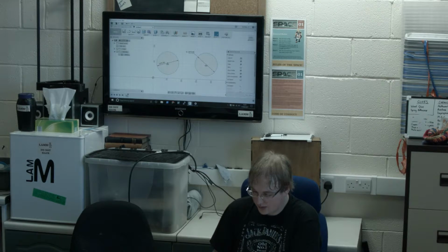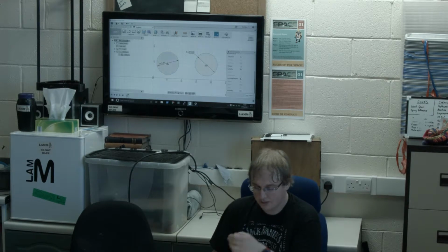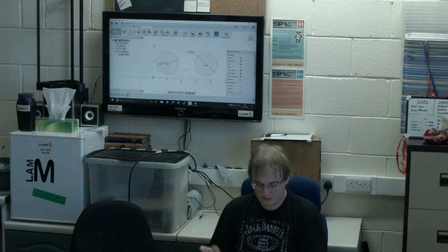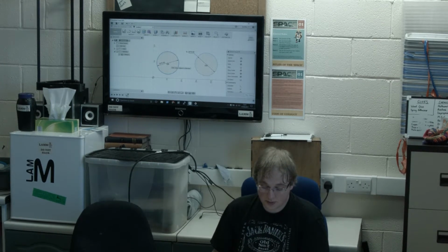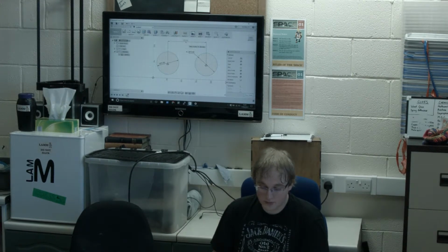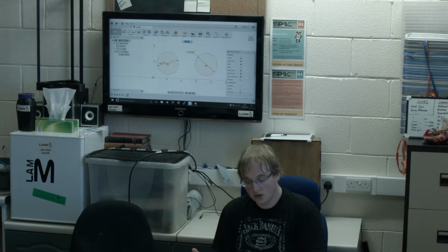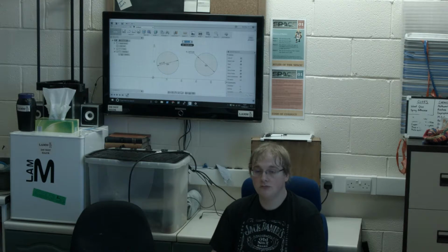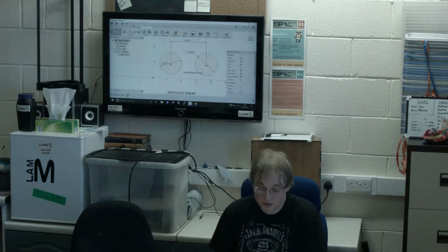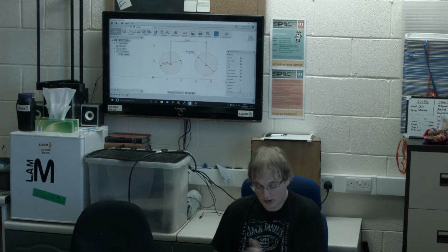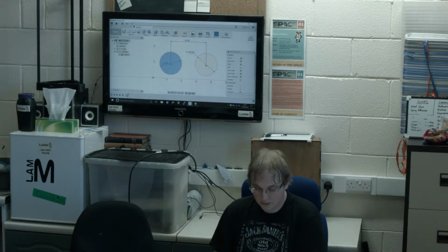The next thing I need to do is to join the two. In fact, let's go for the distance between them, because joining them is a bit easier. As earlier, press D, and that will pull up the dimension tool. Click once, click twice, and now we have a dimension between the two. Let's pick a random number, 120. There we go, that's now fixed at 120. So now they're constrained horizontally and vertically, and they will forever be linked like that.